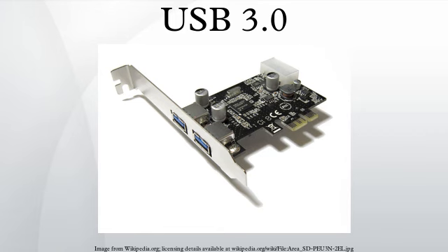Adding to existing equipment. In laptop computers that lack USB 3.0 ports but have an Express card slot, USB 3.0 ports can be added by using an Express card to USB 3.0 adapter. Although the Express card port itself is powered from a 3.3 V line, the connector also has a USB 2.0 port available to it. However, this USB 2.0 port is only capable of supplying the power for one USB 3.0 port. Where multiple ports are provided on the Express card, additional power will need to be provided.